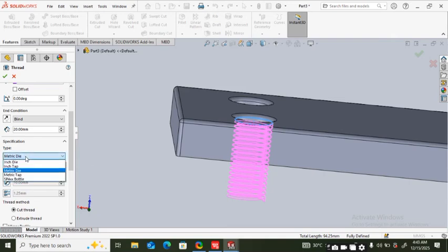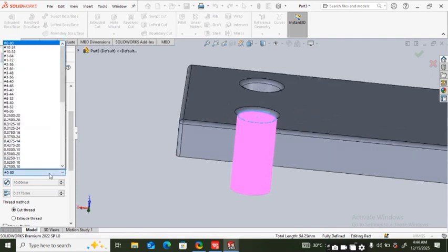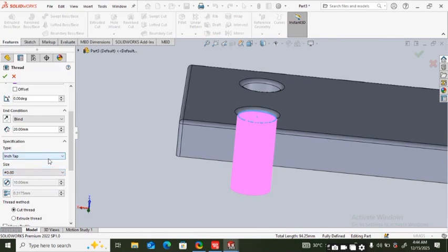And also we're going to have to change it to metric tap. So anything that the bolt or the screw will get in contact with needs to be in metric tap, not in metric die. So as compared to the bolt, we're going to have to change to metric tap. Okay, sorry, this is inch tap. There's a mistake somewhere. It's supposed to be metric tap, not inch tap. That's a mistake.